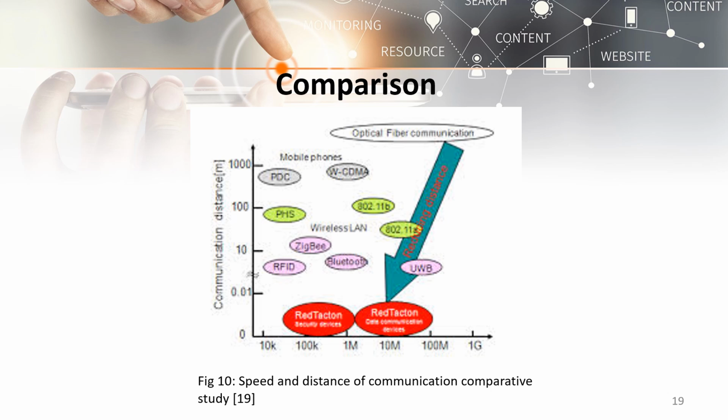Receiving data with such a system is more complicated because the strength of the pulses sent through the electric field is so low. Now, RedTacton solves the issue by utilizing a technique called electric field photonics. A laser is passed through an electro-optic crystal, which deflects light differently according to the strength of the field across it. These deflections are measured and converted back into electric signals to retrieve the transmitted data.